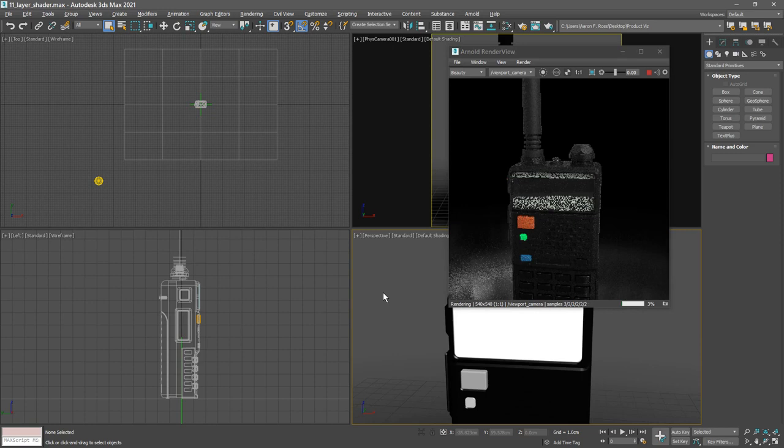This is happening because the back surface of the glass is exactly coincident with the front surface of the LCD screen. We can just move that glass forward a little bit in order to create a gap. Select the glass object, go to the Move tool, and we see a Y position of 1.688 centimeters. Let's move that forward ever so slightly. Set this to a value of 1.687 centimeters. And now we've created enough of a gap there that we don't have that problem, which is technically called Z-fighting. That's when the renderer doesn't know which surface is in front and which is behind.